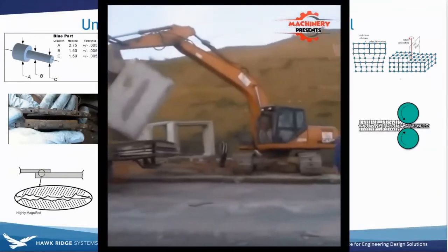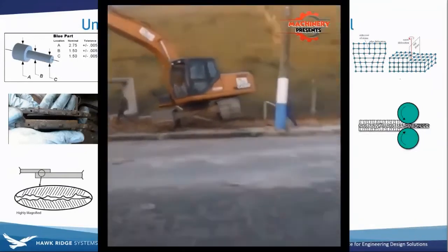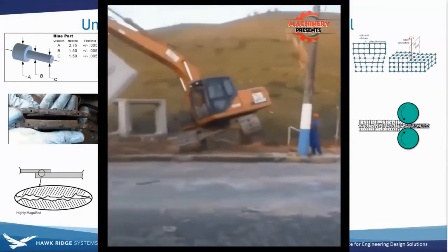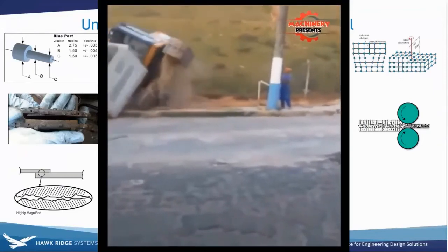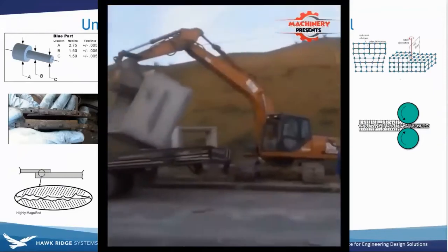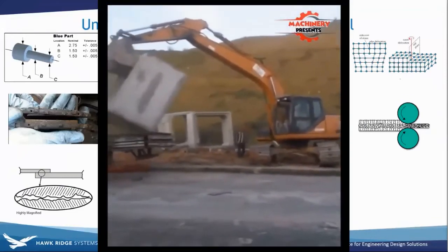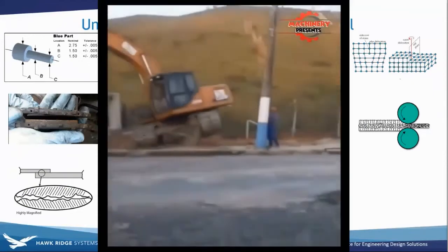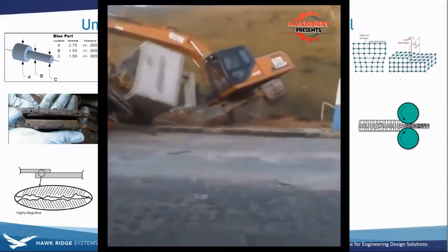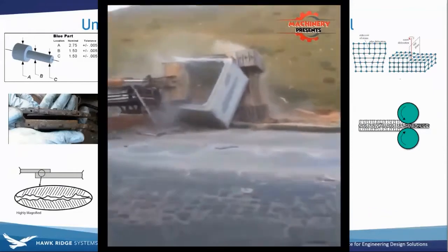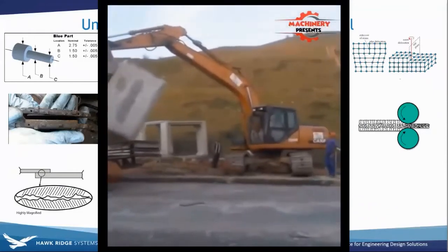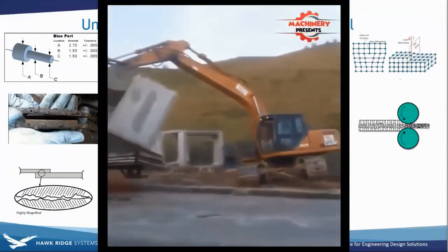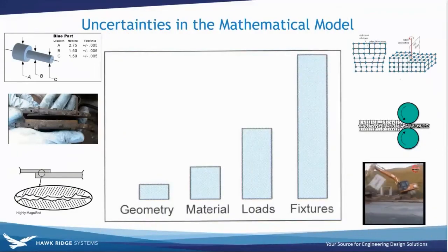With known use cases, it's hard enough to create equivalent forces, but it's almost impossible to account for misuse and abuse of products. Someone will always try and use the product in a unique way, and predicting all the force magnitudes and directions is near impossible. This uncertainty of the unknown adds a significant amount of error, so overestimations of loading and factor of safety constraints are used to compensate for misuse and abuse.